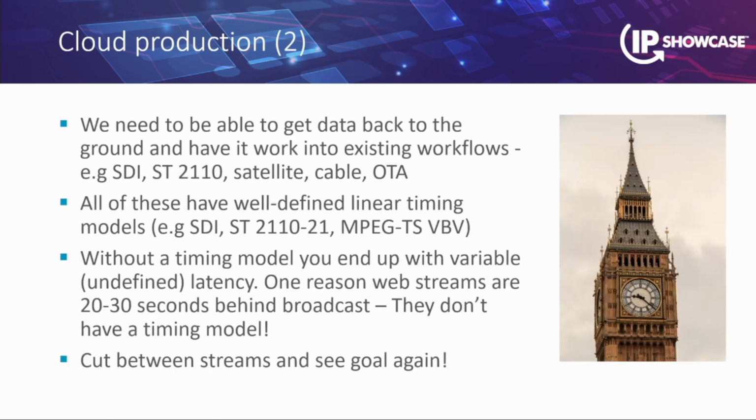And one of the things we need to be able to do is get data back to the ground and have it work in existing workflows. SDI, 2110, and for distribution, satellite, cable, over-the-air, terrestrial television. What's different is all of these have very well-defined linear timing models. SDI, ST 2110-21, MPEG TS VBV. Certainly SDI and TS VBV have been around for 30 years, really well understood. 2110, newer, but still a very rigorous timing model.